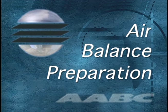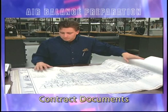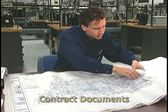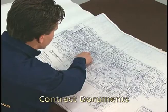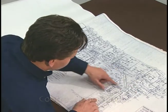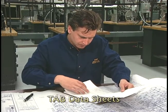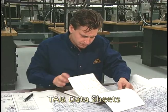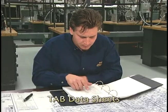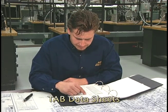Air balance preparation. Before setting up the fan for testing and doing pitot tube traverses, the technician first reviews the job's contract documents. These documents include the mechanical and control drawings, project scope, equipment submittals, and job specifications. From these documents, the technician determines what TAB data sheets are required and what tools and instruments are needed for the job. The contract documents provide much of the required preliminary information, and the technician will enter this information on the data sheets before going to the job to conduct the site inspection.